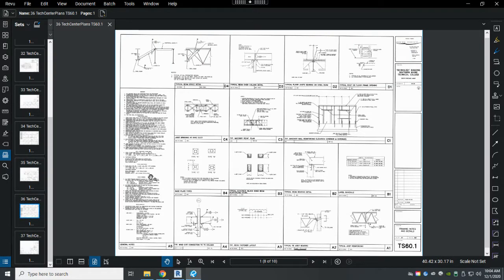We do have a section here that, I think, has some of the soil bearing capacity that was done on the civil that's included in the set to help determine what size pads and framing members and things like that need to be provided for holding up the structure, because obviously the soil bearing has a lot to do with that. So we're going to take a look at that.